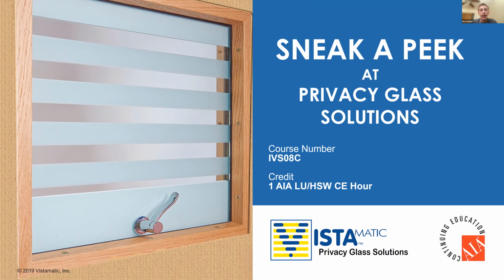Next question, can you have the same lighting conditions on both sides? If this was pertaining to the electric switchable privacy glass, yes, you can have the same lighting condition. What we can do is share the manual that describes 4 different scenarios of ideal lighting condition and non-ideal lighting condition. So basically, you don't want to have very dim light on one side and very bright light on the other, and you also don't want to have direct light directly over the glass, because that can contribute to a little bit more of a haze factor. But equal light intensity on both sides is more optimal.